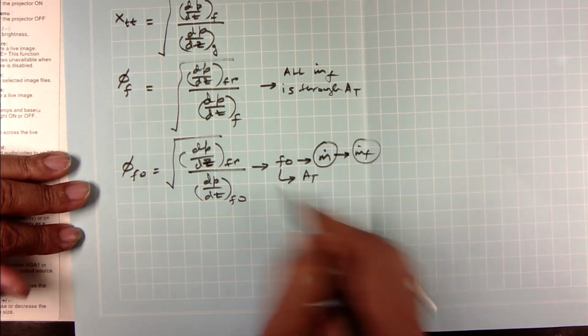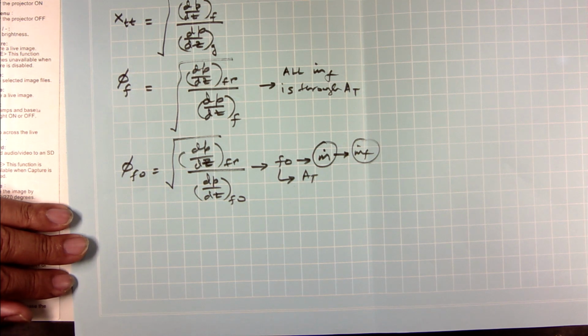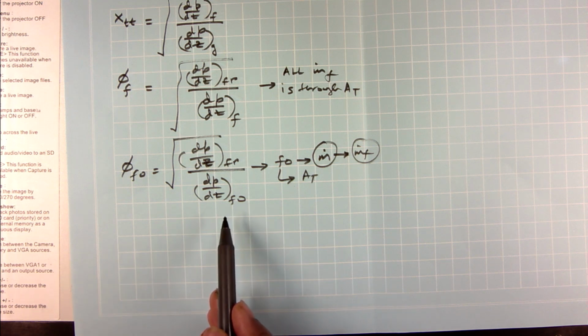This is easy to figure out, right? If I assume single phase flow, so let us say I have 10 kilograms per second flowing through the pipe, 2 kilograms is vapor, 8 kilograms is liquid. Okay. Now if I assume that whole 8 kilograms is flowing through the total cross section of the pipe, then it would be dp dz f. Okay, versus if I take the 10 kilograms per second and all of it is liquid and all of it is flowing through the total area, that is your dp dz FO. Does that make sense? Okay.